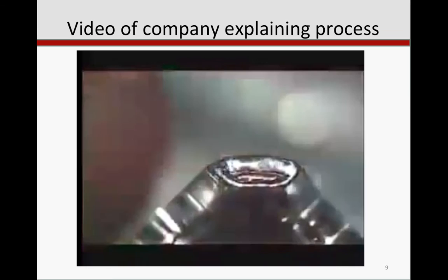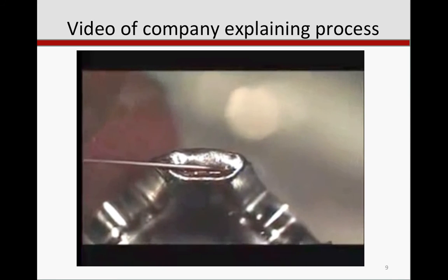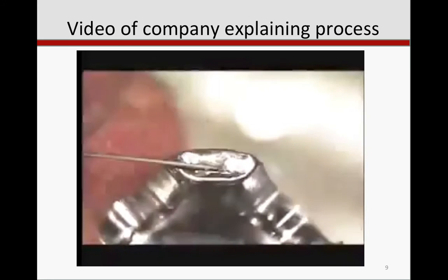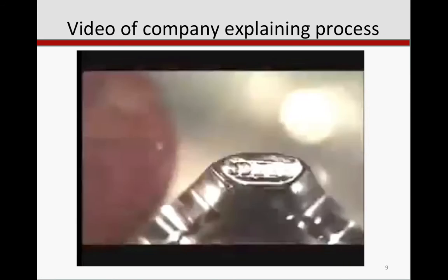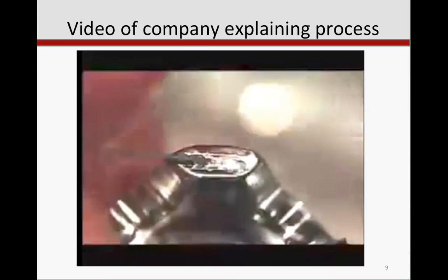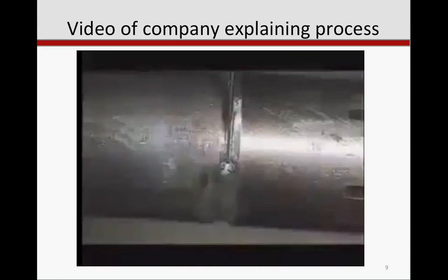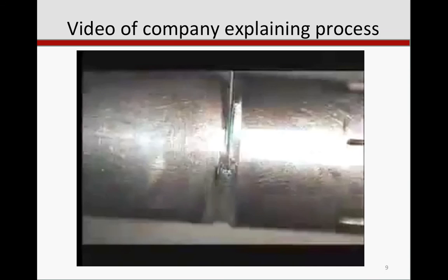Micro laser welding allows us to repair damaged areas of the smallest size. We can create a bead of weld as small as 0.02 of an inch wide, yet also do large buildups when the situation is called for. One of the main advantages of laser welding is the extremely small heat-affected zone around the weld. This allows us to repair a weld in the middle of a detail with no distorting or warping of the surrounding areas, which is typically the problem when using other types of welding processes.